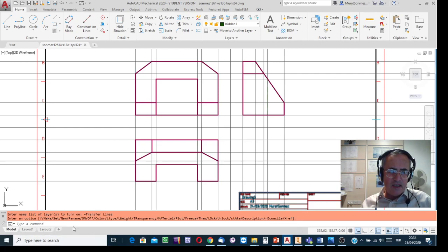Click on the layout tab, write the base view command, the view base creation command, and go ahead. Toward the end of this class work, I'm going to demonstrate once more how the views are created in AutoCAD, not drafted. For drawing the views, we use transfer lines and the coordinate axes, and then join the images of the characteristic points.